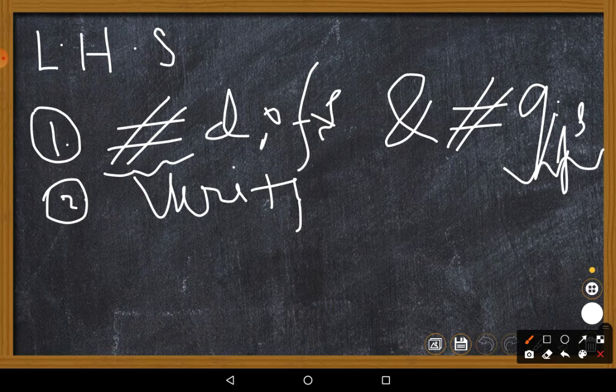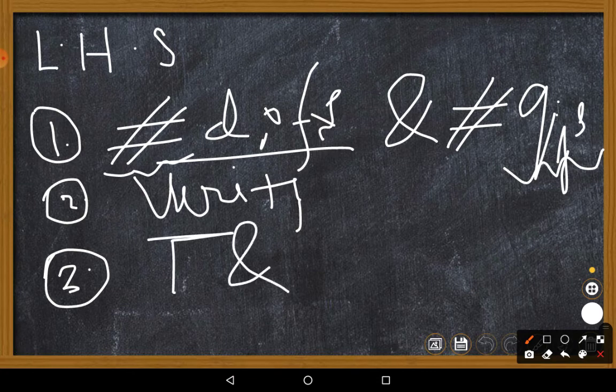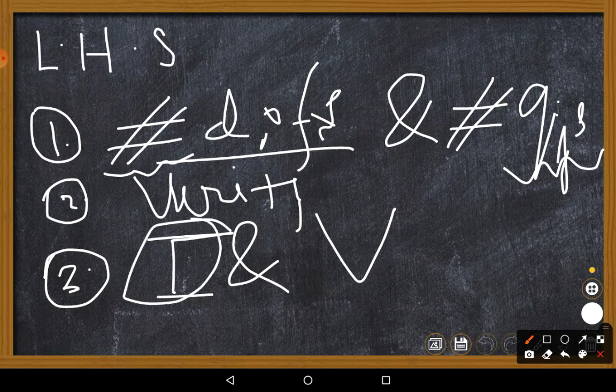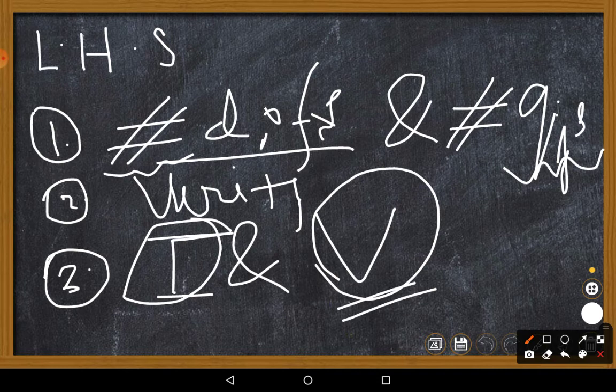If your answer to the test of holonomicity is a no, then you cannot apply this approach. If it is a yes, that means the number of DOFs is equal to the number of coordinates you have chosen to describe the system, which means it is holonomic, which means you can proceed with your approach. Now the third step is computing T and V separately for every rigid body in the system. You find T for every rigid body in your system, add them up to get the final T. It is the summation of all kinetic energies of the system. And you find the V for each rigid body in your system, add them up to get the final summation of potential energy of that system. This is very simple. This idea is from the basic physics you have learned so far. And now you simply compute.